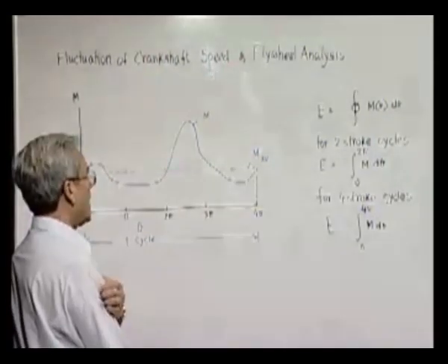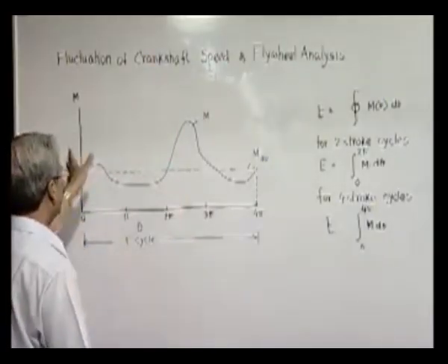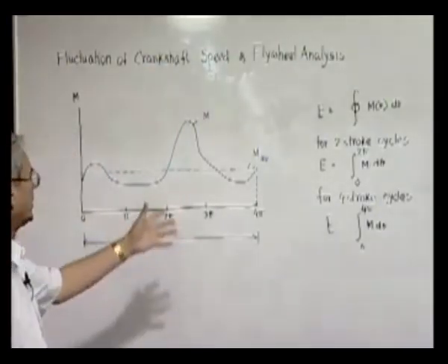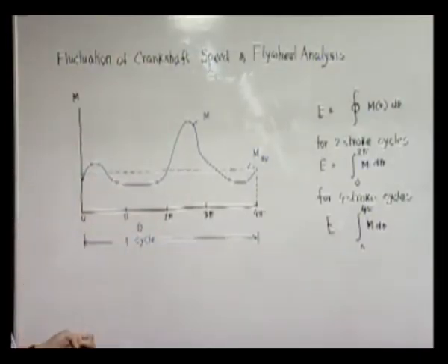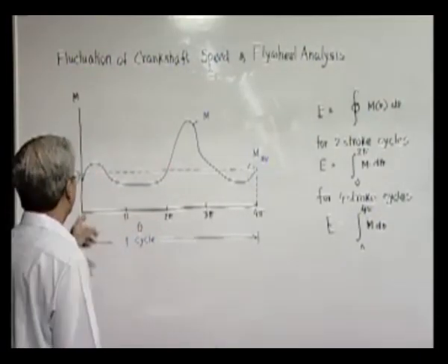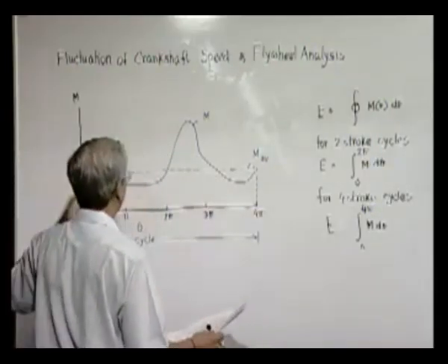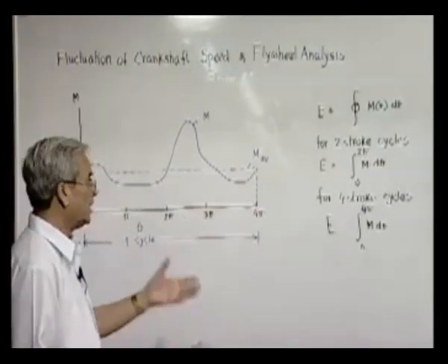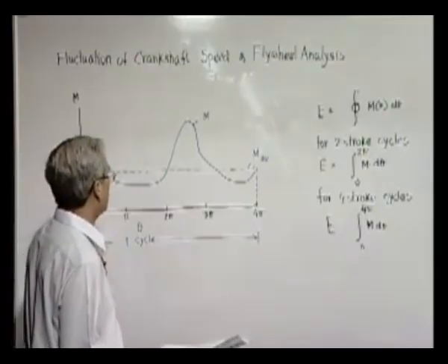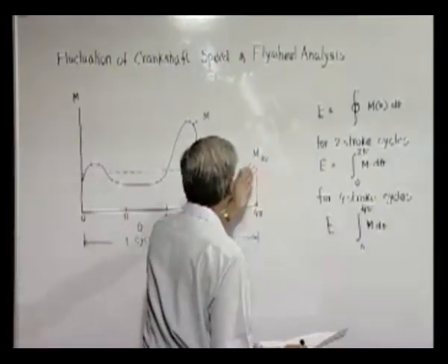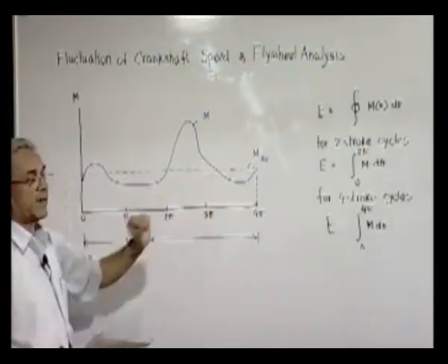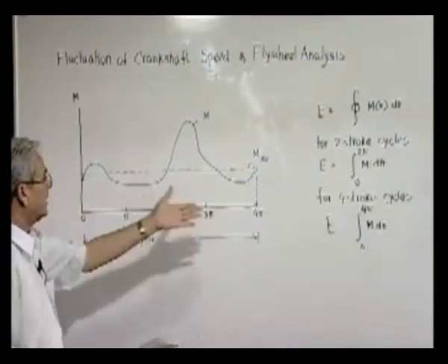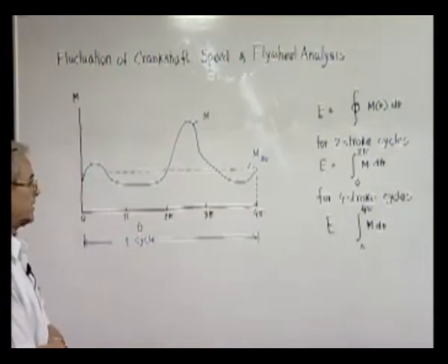In case of starting, either it increases, or when it is less than the power utilized at the output end, then it will gradually go down. So in steady state operation, the resisting torque, which we have assumed constant in this particular situation, must be equal to a value such that the total work consumed by the load is the same as the total energy produced in every cycle.